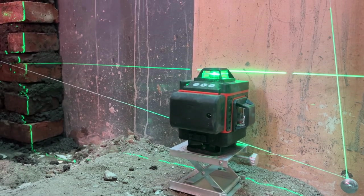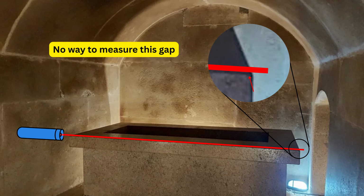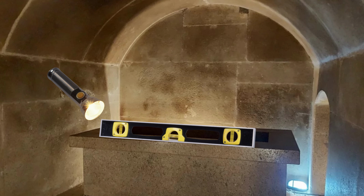A laser line from a construction laser or a line level projects a plane of light. When you see that plane intersect a surface, you're just checking alignment in space, not how far the surface deviates from true flatness. If you align the laser to graze along the top of a sarcophagus lid, the bright line shows where the surface meets the plane of light. Any dips or humps might appear as shadows or gaps, but only if they're large enough for your eyes or camera to perceive. This is analogous to using a long straight edge and backlighting. You're only seeing irregularities beyond a few tenths of a millimeter, depending on distance and lighting.